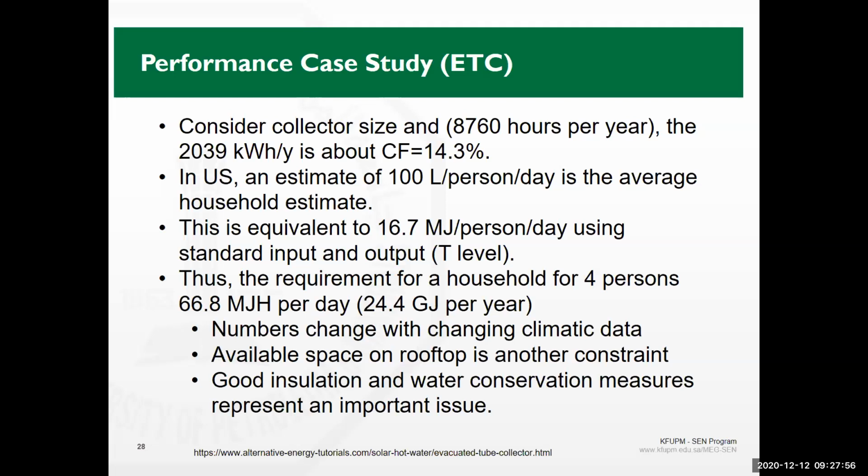So, Doctor, one collector can heat how many liters? Now, the answer is I cannot give you a number for this, because it depends on what the flow rate of the water is and how much energy the collector is exposed to. A collector here in Saudi Arabia may do work equivalent to 2 or 3 collectors in other places of the world. So it depends on how much energy is falling onto it and how much water is flowing.